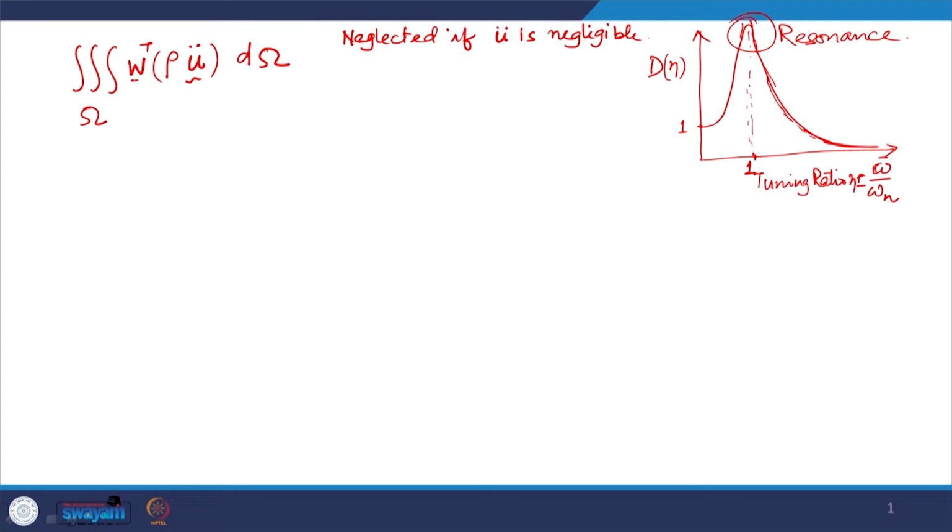All of us are familiar with this phenomenon of resonance. This response is close to static behavior, so this range is known as quasi static, and that is when the dynamic effects can be ignored and the problem may be analyzed more or less as a static problem without bothering about dynamic effects at all, safely.